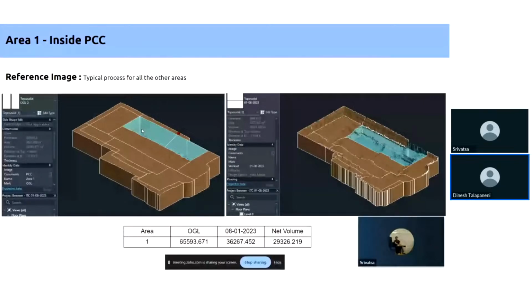The right side is the scan after maybe a couple of months or 3 months; I just put it in for a more graphical understanding. When you see this profile, it has all been excavated, and when you compare, it gives us the exact quantity of work that has been done and executed.